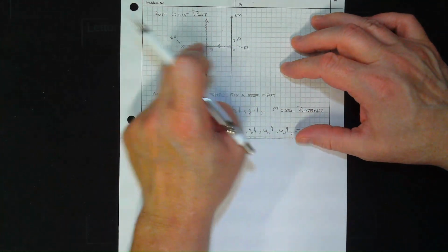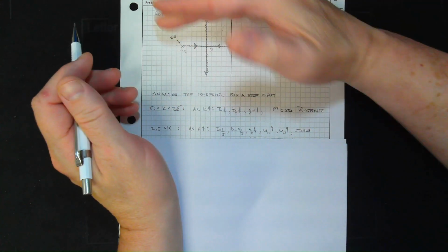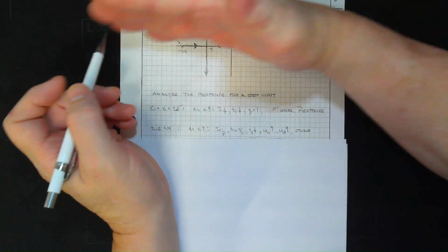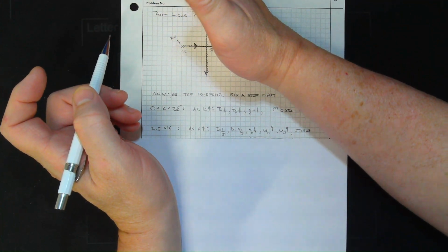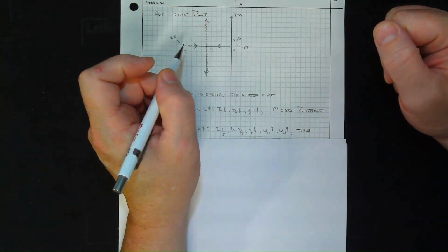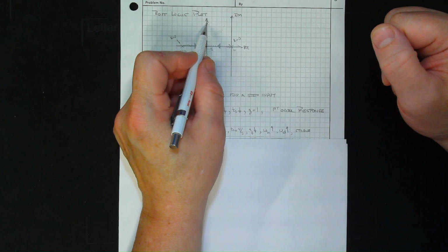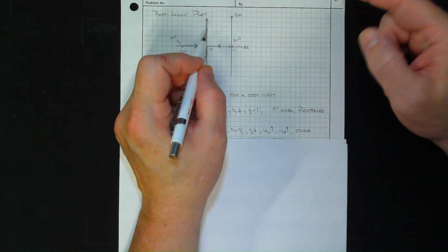Okay. Along this axis, we have damping is 1. Along here, the imaginary axis, damping will be 0. So if you were to track a root, it's going like so. So damping is going down, down, down, and as it continues to go, it can get to be very, very small. So damping's going down. That means the amplitude of the oscillation is going way up.